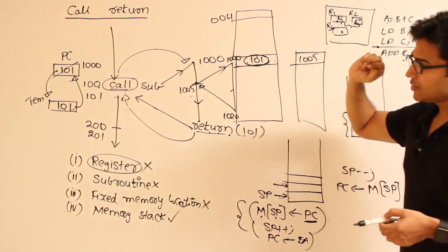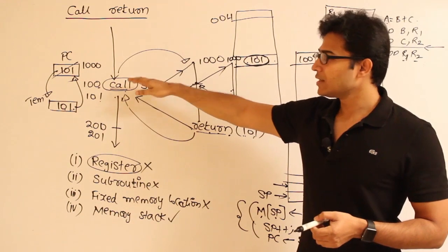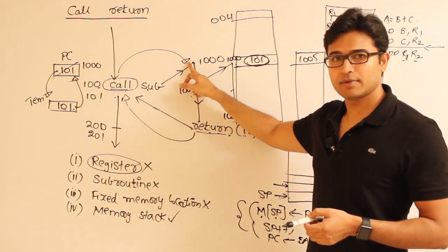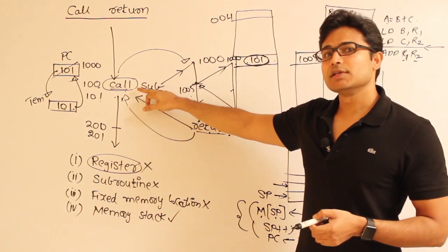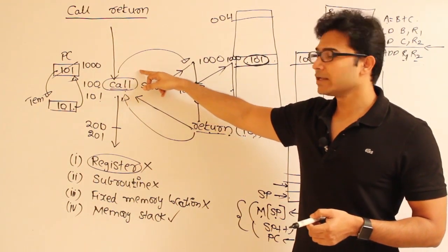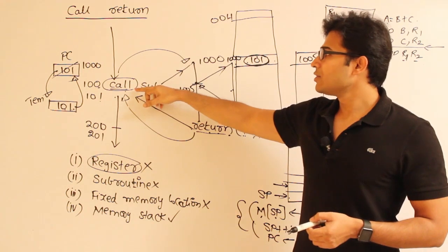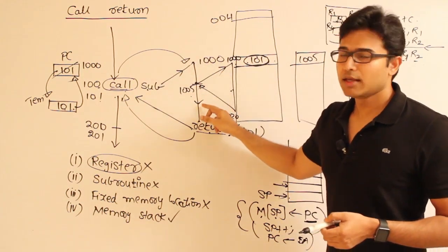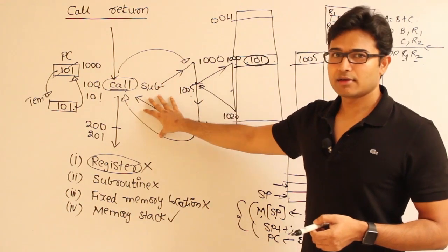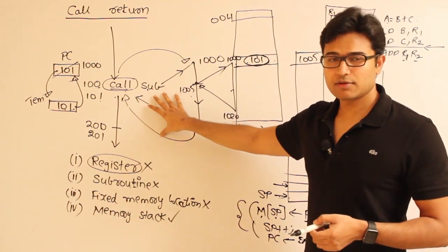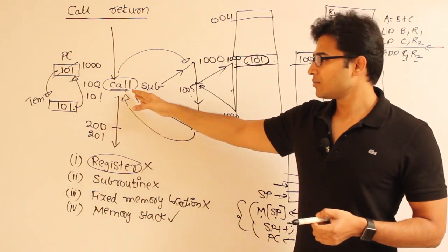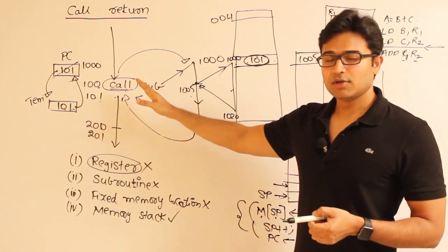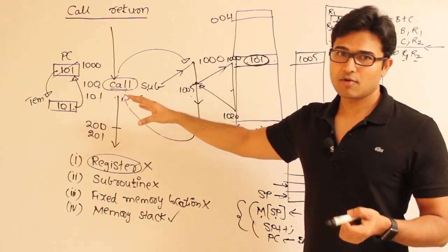But when you are changing the program flow because of internal events, since this program itself is calling some other program, it will never try to use the registers which have been used earlier, or in case it is going to use those registers, it will not use them here. Got it? Therefore the program itself will take care. So the main thing that you are supposed to save here is the return address. You are supposed to save the return address in the stack and then get it back, right? You need not save the program context.